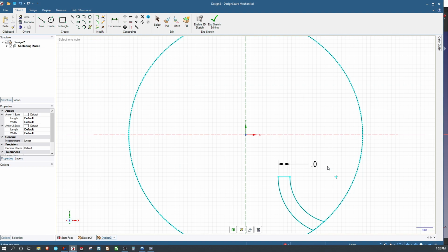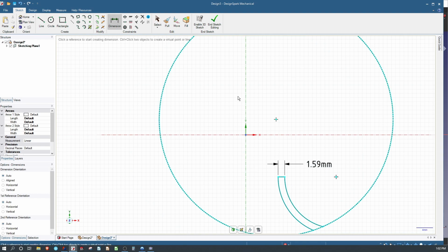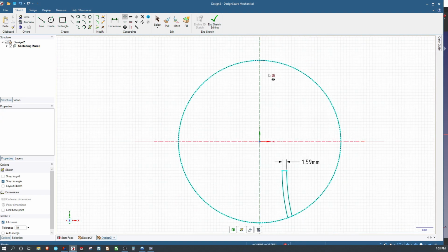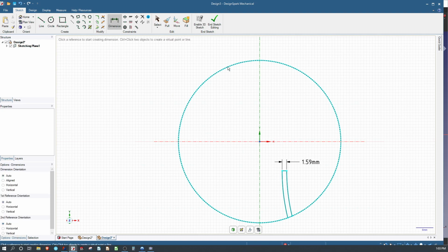I'm going to say 0.0625 times 25.4, because I know the dimensions of my compressor in inches. We will now grab this coincident. We'll choose this center point, and that will make sure that my circle is coincident to my origin, right? Great for orientation. That would actually be very critical for coming up, that your circle has the origin as its center point.